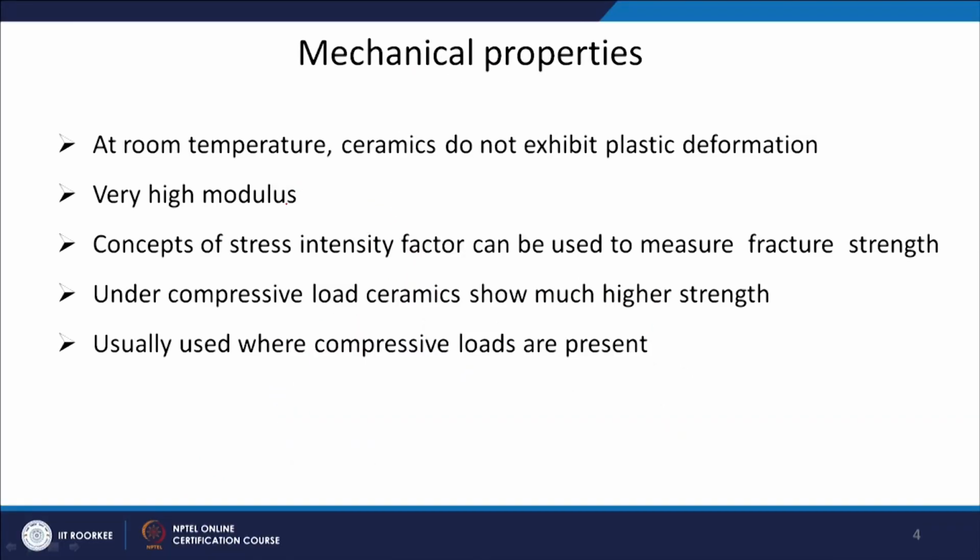So, the deformation here cannot be through dislocation movement, and that is why ceramics usually fail without any plastic deformation, although they have very high elastic modulus values. The concepts of stress intensity factor, which we discussed when we were discussing fracture, can be used to measure fracture strength in the case of ceramics.